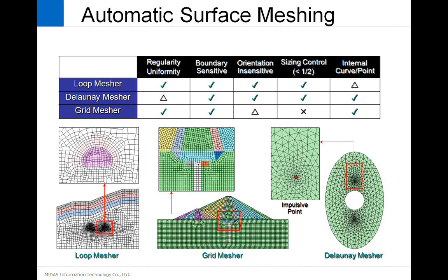And in all of these meshes you can either go for a triangular, which is actually 3-node 2D mesher, or you can even go for a higher order mesher creating 6-node 2D meshing. But along with the triangular low order and the high order, you can also go for the 4-nodal quadrilateral and even the high ordered 8-nodal quadrilateral meshing using auto mesher.